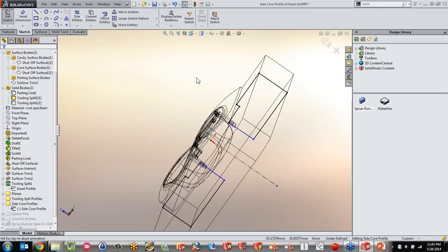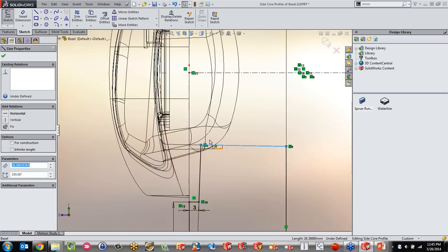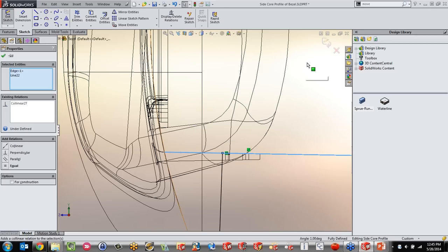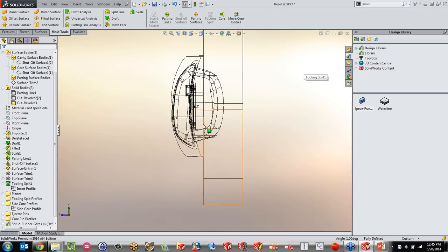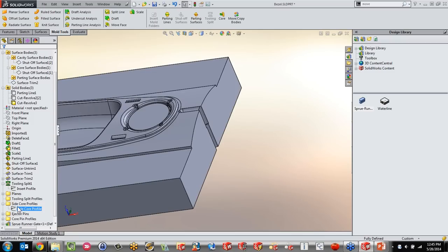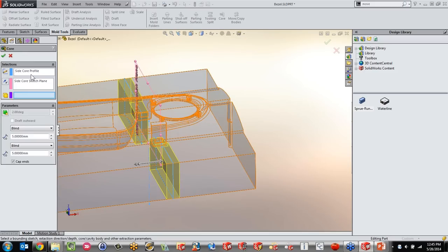Now I can create a relationship between what I need in here for the slider over here, with the column. What this core tool will do is, if I select that sketch and hit the core, it knows the sketch, it knows it's going to create these cores out of here, and then it's just looking for a dimension that is going to extrude out per side of that sketch.